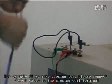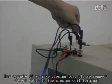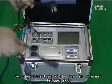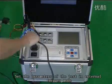For example, if we make a closing test, please connect the detect cable to the closing coil terminal. Set the parameters of the test in external trigger mode.